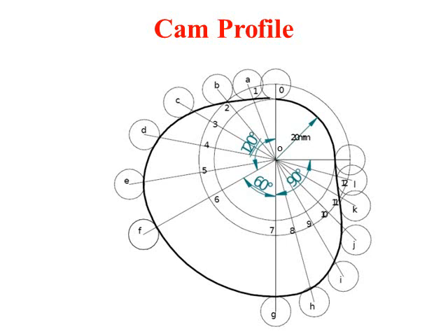But in this particular sketch, in the PPT, they are not joined, but we have to join them. Join A, B, C, D, F, G all together by dotted lines, by a smooth curve, and join it to O. Join it to that point O. So that becomes the pitch curve.